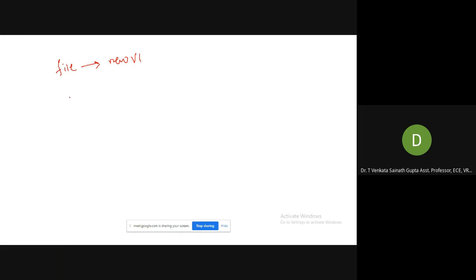After this, you will get two windows, and to align them, you press Control plus T. Whenever you press these two buttons, the windows will be aligned side by side. The two windows that you will get are the front panel and the block diagram.